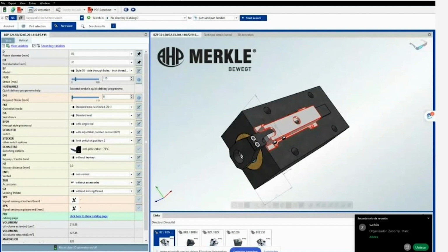But if you have a cylinder with 300 or 400 millimeters, this is a completely different story. That is why we go down to 160 bar. This is what we recommend, and we see it as difficult in larger strokes for a tie rod to sustain 210 bar.